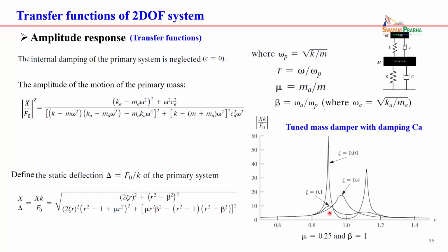So, for example, you increase the damping for this case study from 0.01 to 0.4, you have this result, right? You can say, oh well, we don't have the risk of the two peaks, but here the performance is not good, right? There's an optimal damping. So optimal damping is a trade-off. You try to reduce both peaks without increasing vibration in the middle.